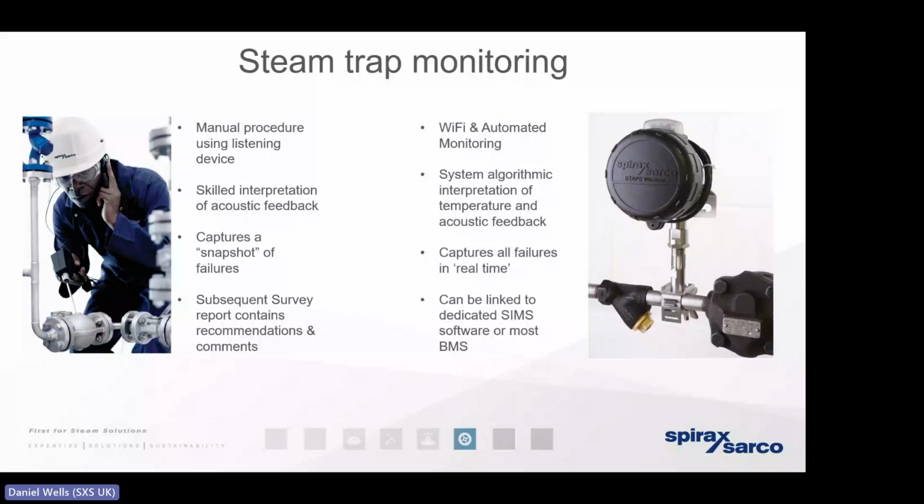But if the steam trap has failed for the purpose of removing condensate from the infrastructure, that's when the condensate is going to slowly back up and flood the steam line. And that's when we're going to get the erosion, corrosion, and water hammer creeping up on us over time. That's when the steam is going to slowly degrade and deteriorate, and our cost of steam is going to increase. So again, it explains the importance of having that appropriate steam trap audit on a regular basis.